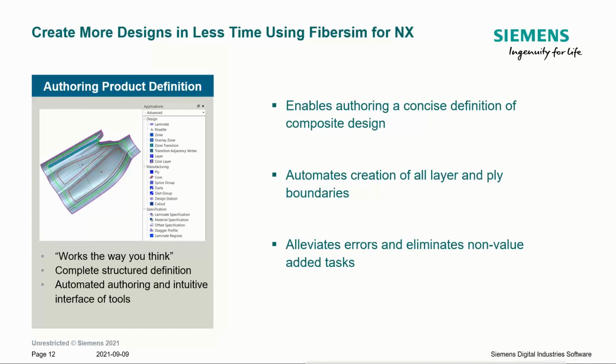One thing to point out is that those glowing curves that you see here on the image on the left, these are virtual curves that Fibersim manages. We're not building a lot of geometry in the background, so the model isn't getting appreciably heavy. I've seen some designs from other tools that you have to create a bunch of closed curves for every ply boundary, and the models get very heavy weight.